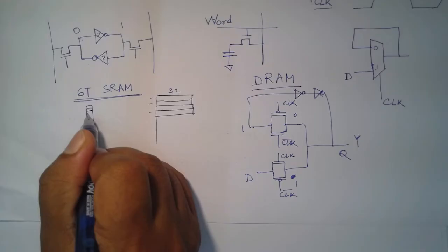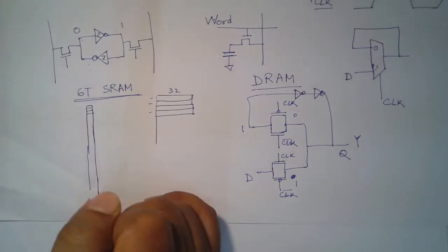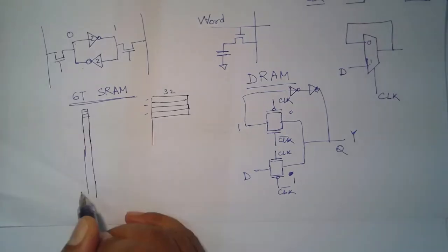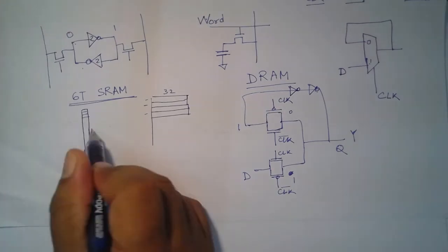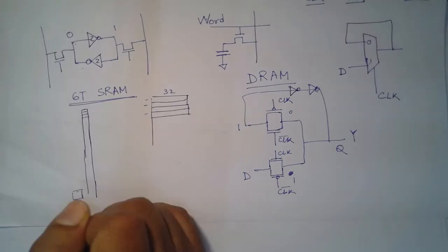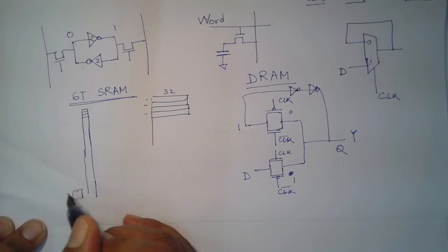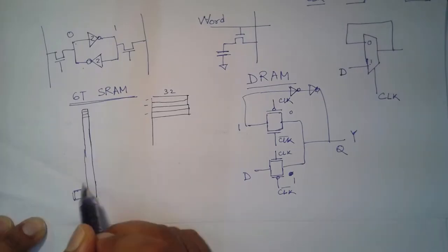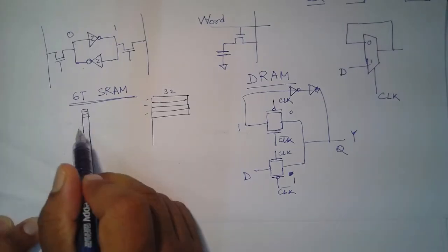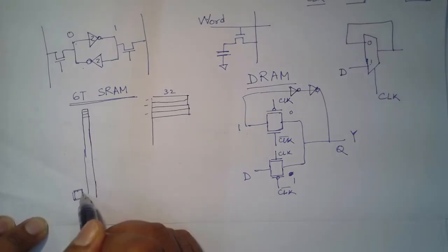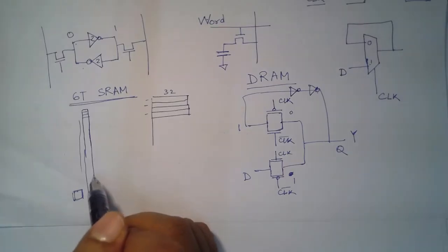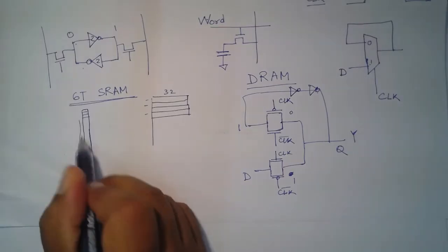32-bit in one row, the structure will look very skewed, and then for reading every row, you will have some address decoder, and you need some connections to all these rows, so that you can read appropriate rows depending on what you need to read. Now the address decoder will be lying somewhere here, and your memory will be this skewed structure. Now the wiring overhead etc. will be enormous, because this structure will be very long. So you will have long wires running from here to here, and long wires are a huge bottleneck in terms of performance. So definitely you don't want to build this kind of a structure.